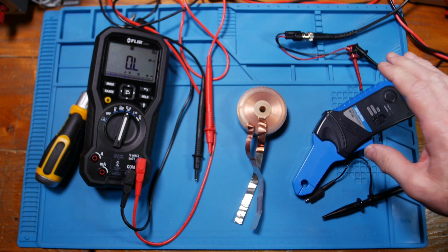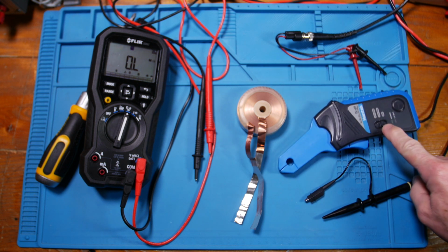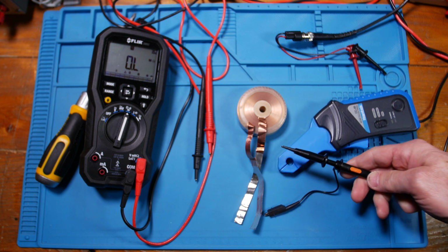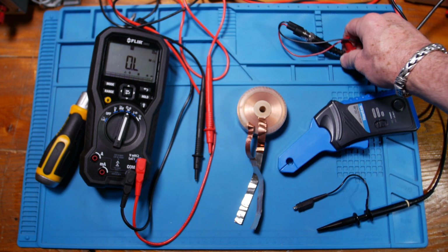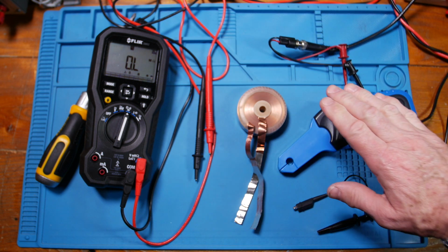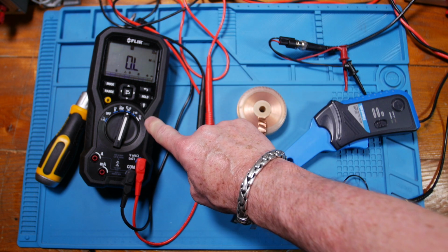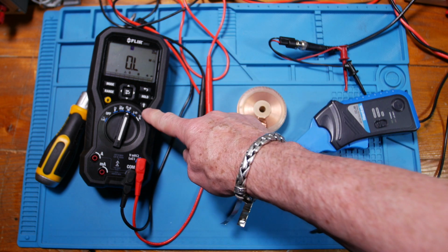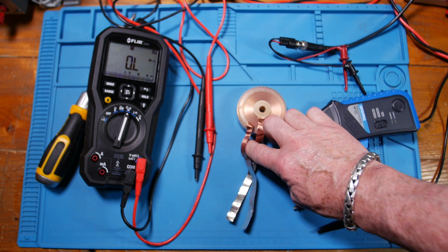Alright, so here are the tools we'll use. We'll use this Handtech CC65 in the ×10 position, and we'll zero it out here. We're going to use a scope probe in the ×10 position, coming from the arbitrary generator from the scope, the GW Instek. And here is the guy we want to measure. And here is a FLIR meter that I just reviewed, the DM92. We can measure the resistance with this guy. We can't measure inductance with it, but we can use the scope. That's the whole point of this.